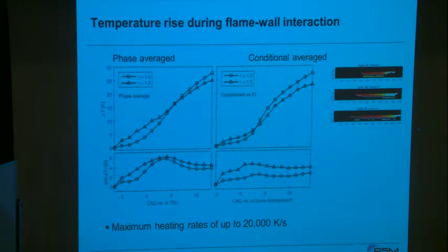Actually, for the phosphor thermometry, we have done that. We have one paper out where we have shown how to develop such an endoscope. But still, you might end up with problems that come from a different side. For example, if you take a full metal engine with all the lubricants, you will have an oil film. And if this oil film is covering your phosphor, then you're in trouble, because that oil typically absorbs UV. And then everything changes. So you have to make sure that these problems are somehow overcome. And that is very specific to the geometry and the system you're looking at.